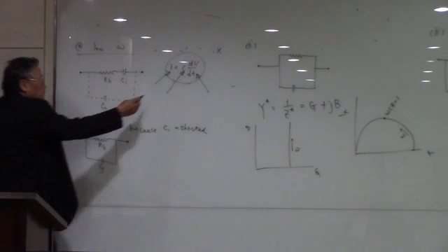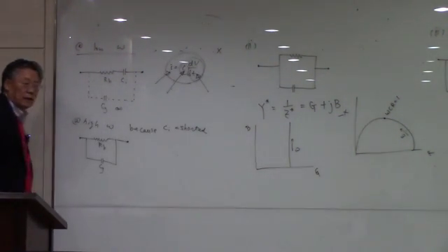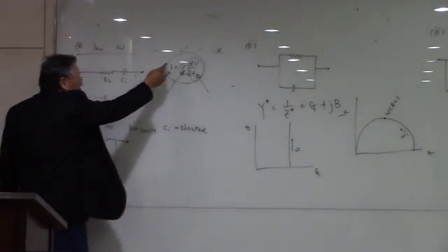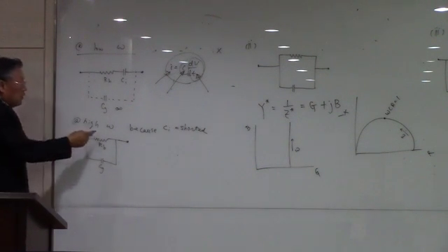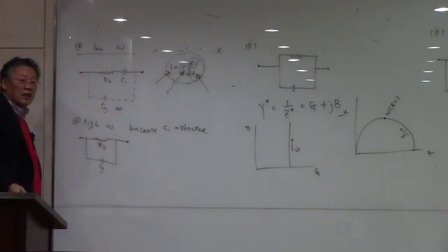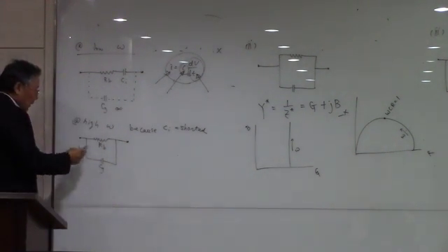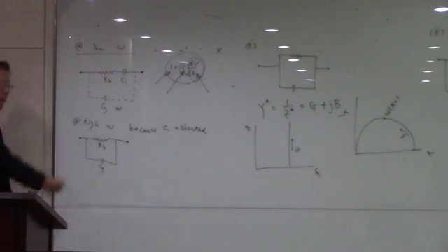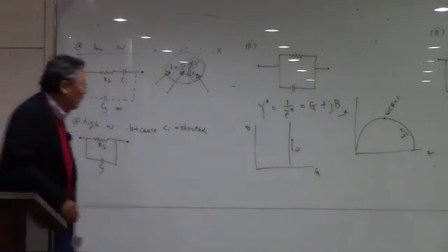See, this is too high, and this is high again. So we have a large current here through this Ci at the high frequencies, so that we can regard this Ci as shorted. Okay, so then the whole circuit is going to be changed to the parallel connection of resistance and the capacitance.